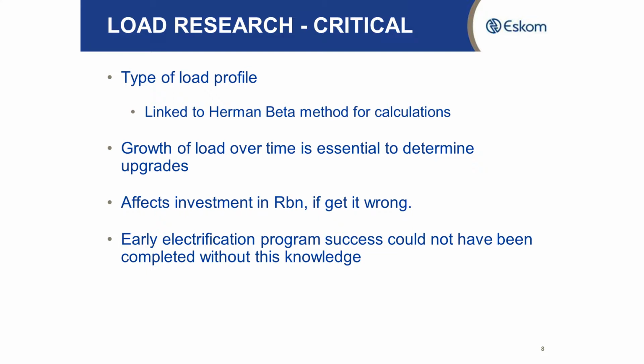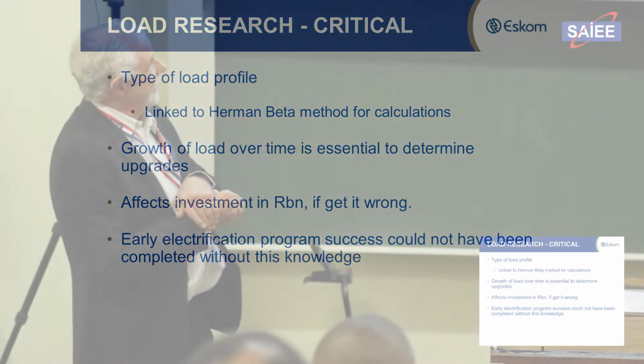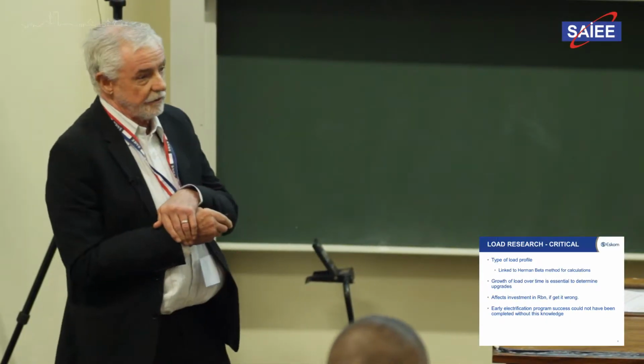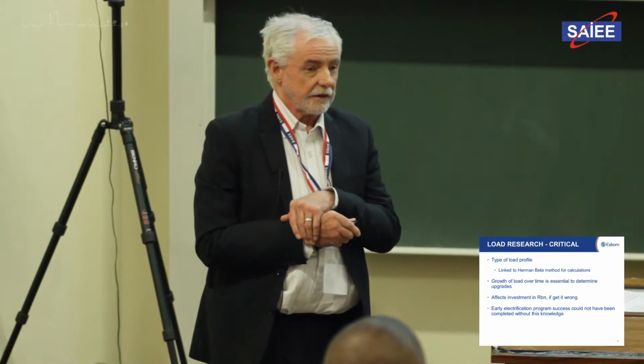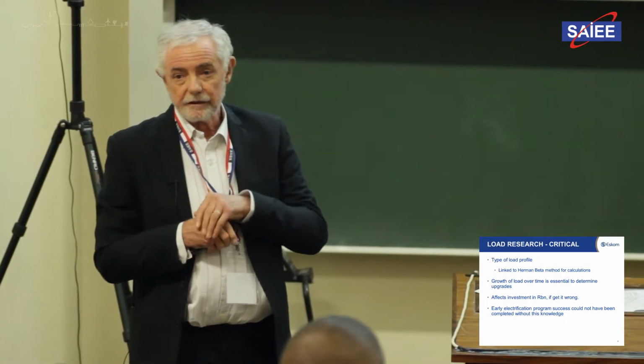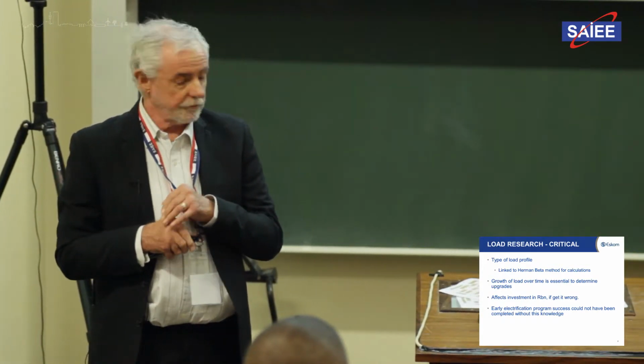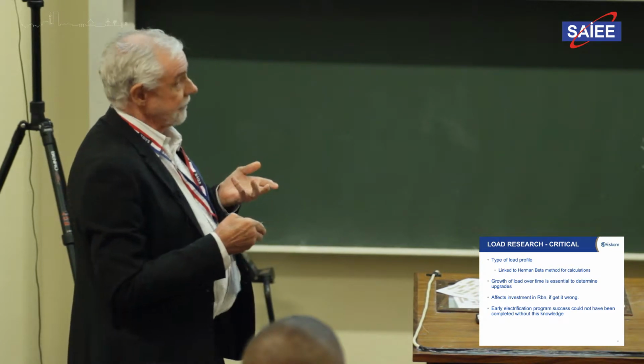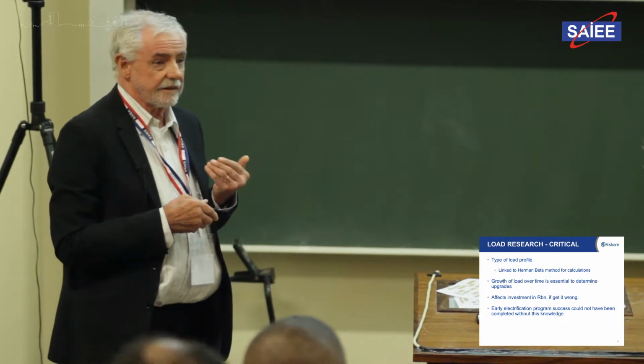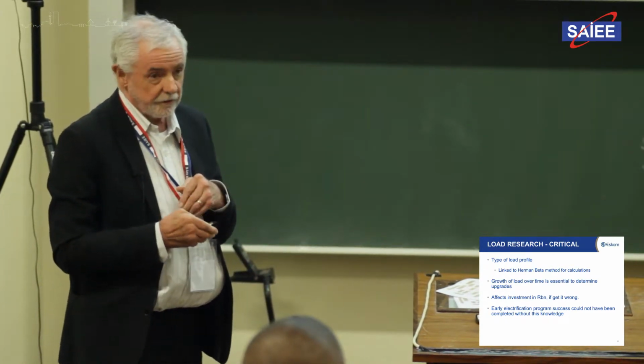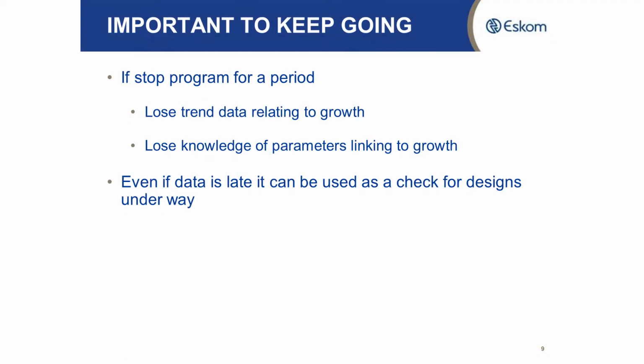If you design at 3 kVA and you should be designing at 1 kVA, you can spend a lot of money with an underutilized network, or vice versa. And we wouldn't have been able to meet our cost per connection without this information that we get from the load research. A lot of our templates, standards, everything has been done based on input from load research.